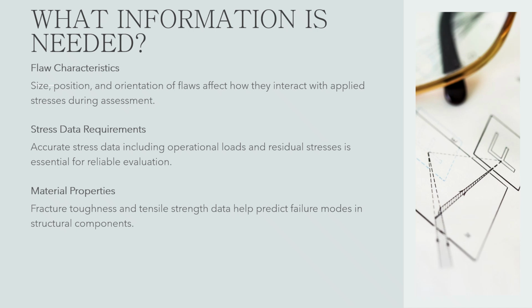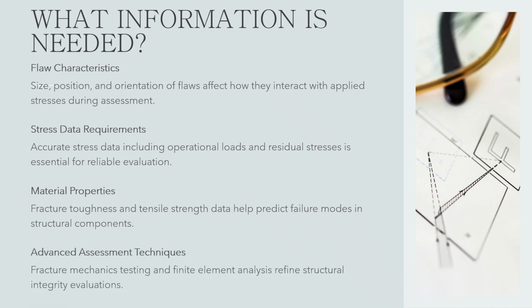Gathering this information often involves a multidisciplinary approach combining stress analysis, non-destructive testing, and material engineering. Advanced techniques like fracture mechanics testing (CTOD), J-integral, K, and finite element analysis (FEA) may also be applied to refine the assessment.